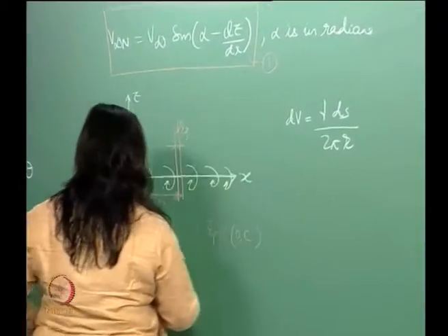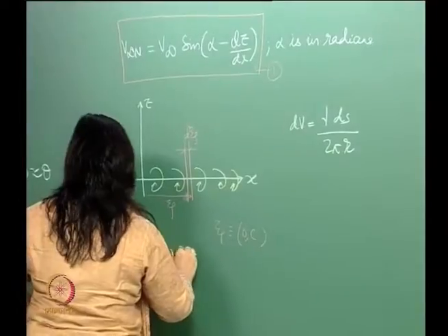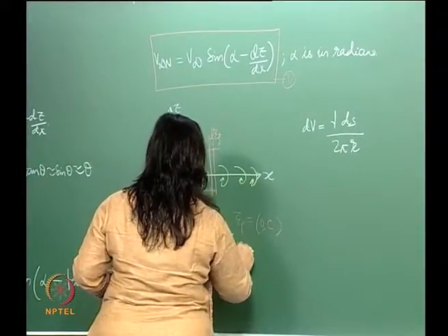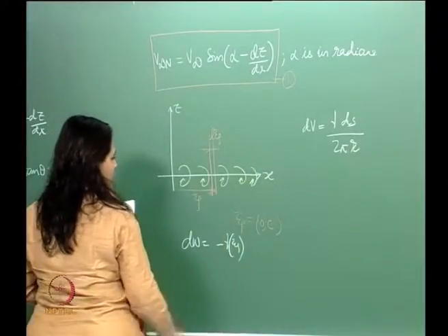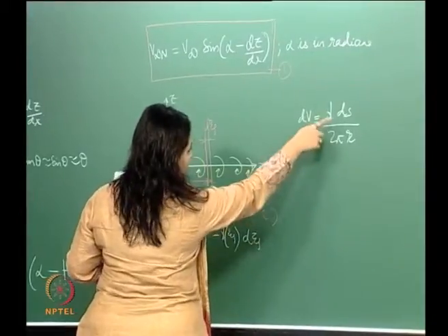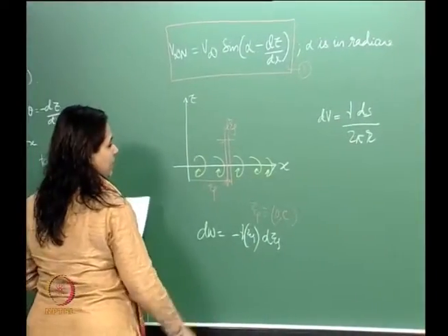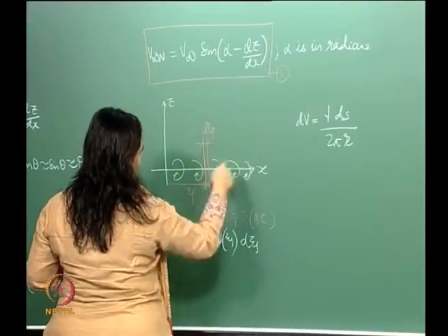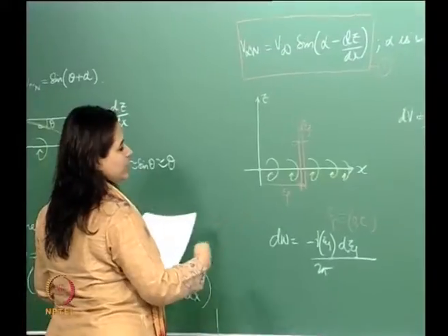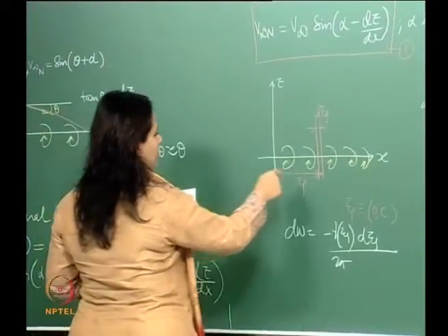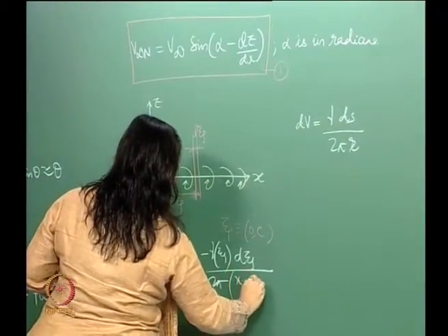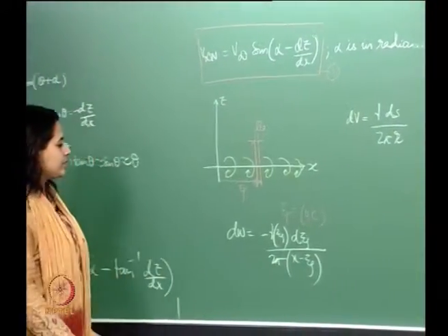The total velocity distribution in this case would be, the gamma is distributed over this, say, z into dc, just going by this expression here. So, dc, which is ds over here, over 2 pi, and r is the distance between any point and the location of this, so it would be x minus c.